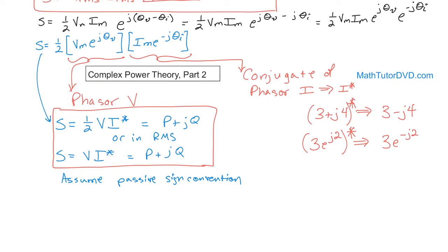If you remember back, if you have a circuit element with something inside of it, and you have two terminals coming out, and let's say this one is the current, and then you have plus minus V. This is how we're going to write the sign convention. When we have the current going through a voltage drop like that, you write it with a positive sign. In other words, I'm talking about the complex power you're calculating. You're just going to write it as V times I because the current is going in the direction of a voltage drop.